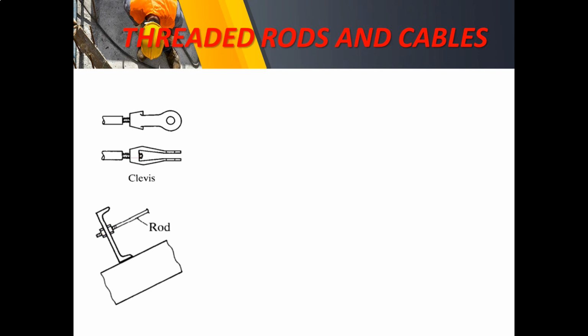Now, with respect to that mentioned stress due to threads, this will be the thread, and there will be a stress area in it. So the stress area will be incorporated in the nominal area. Of course, the nominal area is that of sections without threads, and the relationship between the stress area and the nominal area is that normally the stress area is only 75% of the nominal area.